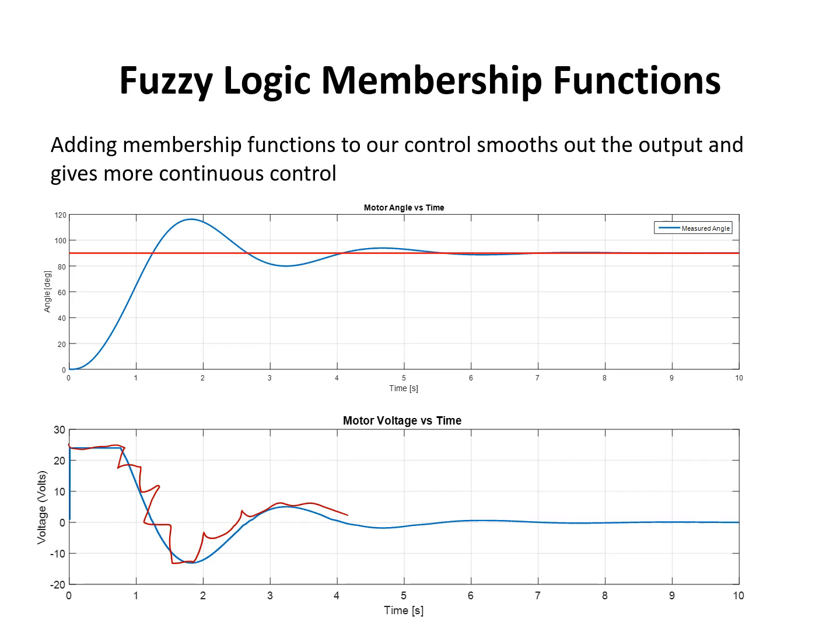which we also develop in control systems in the 4th year, specific ways of implementing PID controllers. And again, specifically note that when you have a derivative term in a PID controller, filtering of the derivative term in actual systems in practice is important. Of course, in a simulation environment, you will not see the noise in the derivative term. It's generally good, if you have a system, to add noise to your simulations to simulate what the derivative term would do if you have a noisy measurement signal.